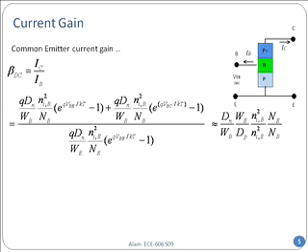As a result, the exponential factor will drop out. And of course, the VBC, as I just said, reverse bias, strong negative number, so that number essentially drops out. It simply collects the electrons that are coming from the emitter. So I have this simple expression. You can see there are some diffusion coefficients of electrons and holes floating around. There is this WB and WE, how long the emitter region and the base regions are, and so on and so forth. So we will take this expression apart term by term, and we'll see how to make a great transistor.